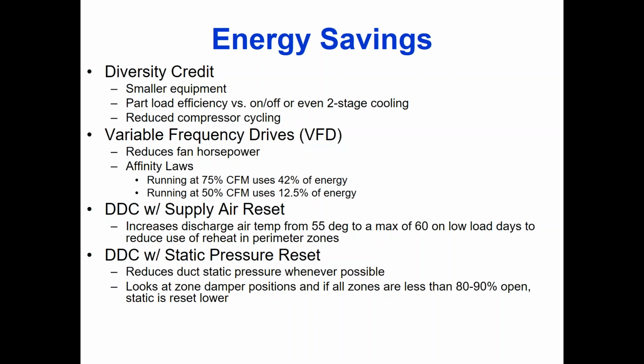And I'm going to keep dropping the static pressure set point lower and lower, which lowers my VFD, which lowers my CFM. I'm going to keep lowering that until one of the dampers gets back to requesting 100% airflow. And when he wants 100% airflow, obviously I'm not able to give you anything more. Your damper's wide open. I'm going to have to raise the static pressure set point to give you more CFM at that point. It's pretty easy to do.